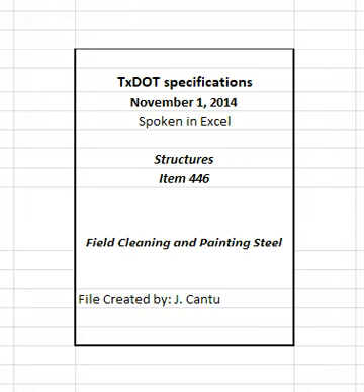For manifesting purposes, the department is considered the waste generator for paint removal wastes generated from structures owned or controlled by the state. Dispose of this waste in compliance with applicable waste rules and regulations as specified above and by the contract. Provide copies of all test reports and transportation manifests to the engineer before shipping waste. Provide signed original manifests to the engineer verifying all steps of the handling and disposal process were correctly handled.